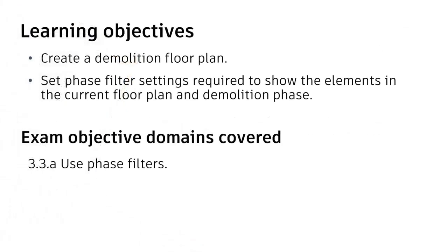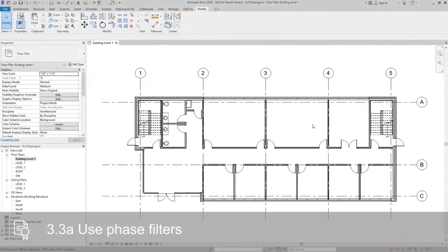In this video, we're going to take a look at phasing, specifically what it takes to create a demolition floor plan, how the graphics are controlled, and the appropriate phase and phase filter settings we need to show the elements that we're looking to show.